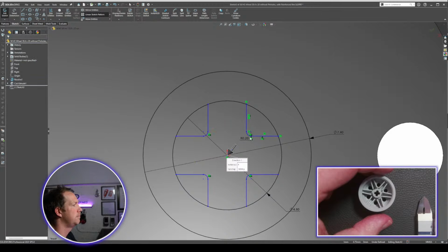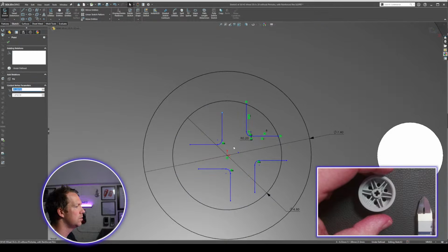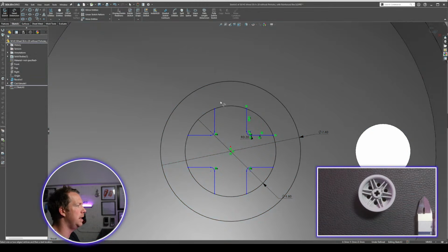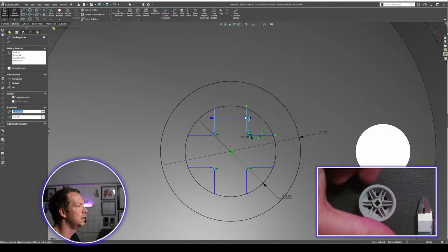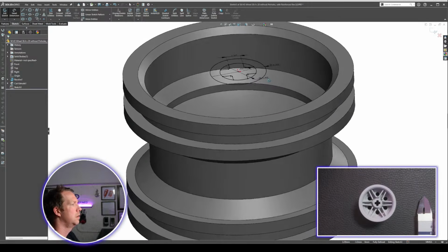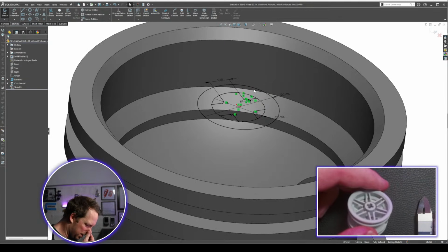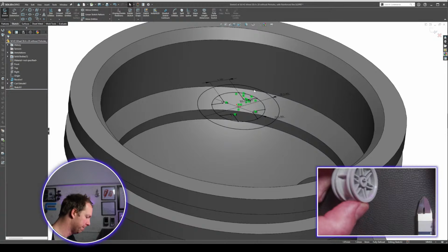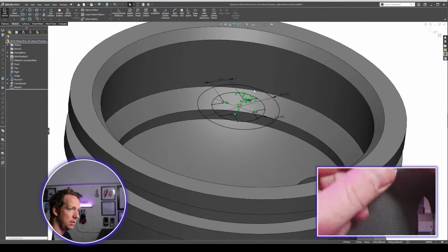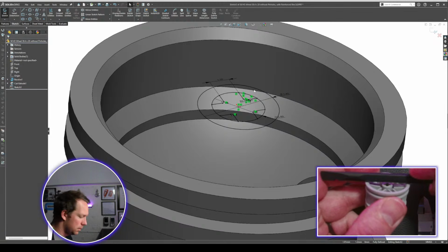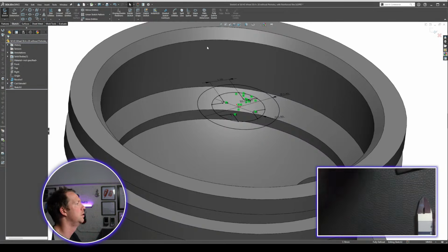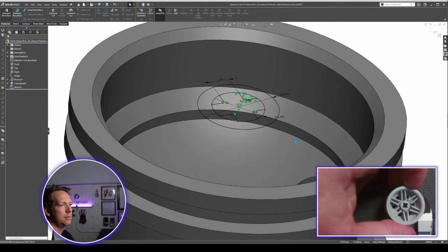Okay, I'm going to grab those and do a circular pattern. This is a sketch pattern. I'm going to grab that origin, that center point, put it there, and then a dimension between the arcs, those line segments. All right, so now I'm going to extrude down, and I can see that this face is not quite at the same level as everything else. It's a bit below. It's difficult to measure. I'm going to eyeball it as 2.5 millimeters.